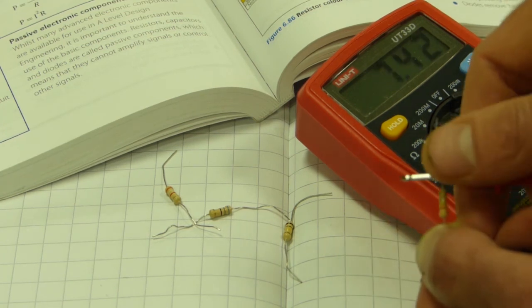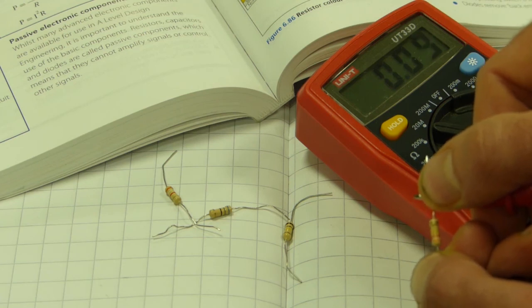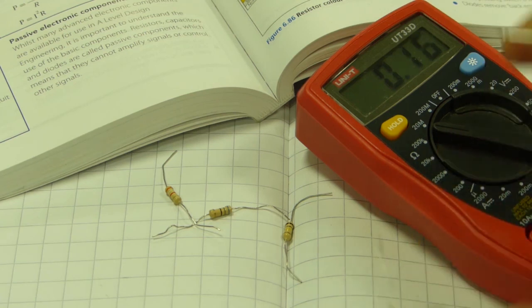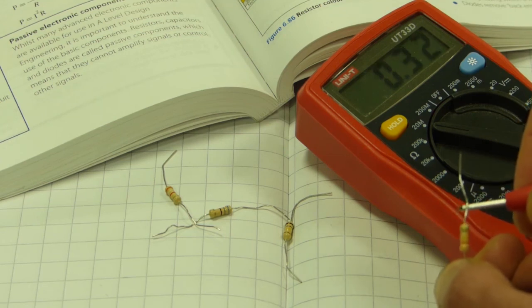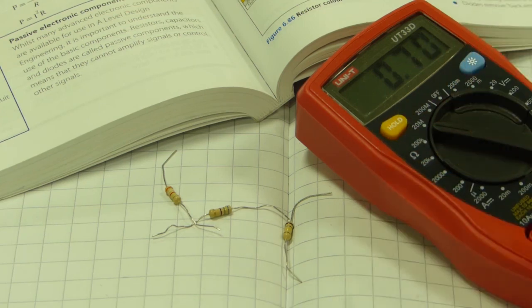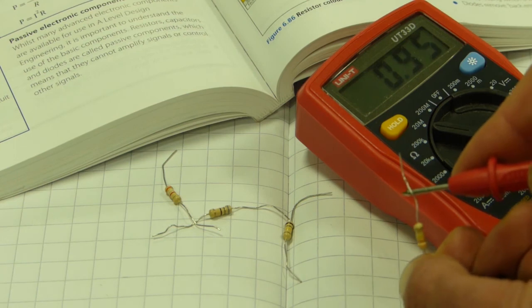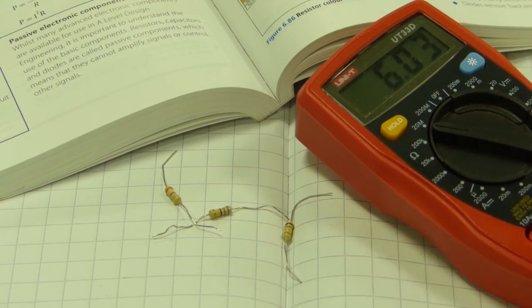By the way, if I hold it with my hand as well, I'll get a completely different reading, especially when you get into the big amounts. Okay, so I am a resistor and I'm making a big difference on that big resistor. So it's a good idea just to touch it with one hand like that. Touch it with one probe, not touch it with both hands like that. So yeah, what have we got there? We've got 0.32 thereabouts. What does that mean?